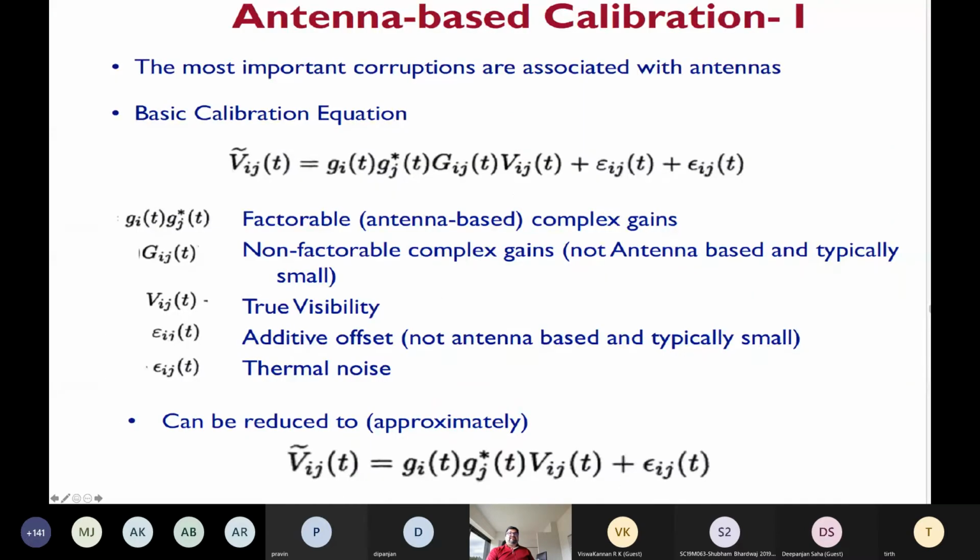Yeah, when you derive this kind of gains, it's actually directed towards the phase center, or the center of the field. However, there are certain effects like the effect of the primary beam itself, and something like the ionosphere, which we'll talk about in just a second. They are actually varying across the field of view. So if you have a particular antenna, it has a particular field of view designed by its primary beam pattern or radiation pattern. So basically across the beam, by doing self-calibration, it is only deriving one solution, which is towards the field center.